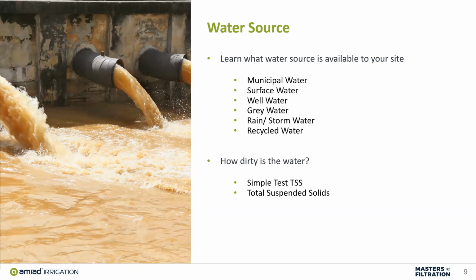The reason why we bring up water source is we really need to understand how dirty the water is. This can be done by a simple test, TSS, or total suspended solids. So we want to understand how many particulates are in the water that we're dealing with.